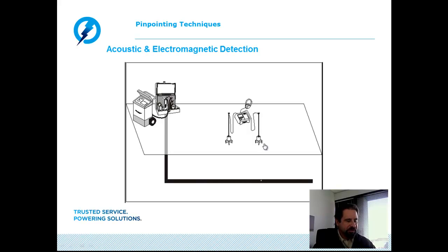If the time difference between when you visually see the lightning and when you hear the thunder decreases, it's an indicator that the storm is coming toward you. If the time period between the flash of the lightning and the audible sound of the thunder increases, this is an indication that the storm is moving away from you. Applying these same principles, the lightning is the electromagnetic surge sent by the thumper, measured on the electromagnetic impulse detector.